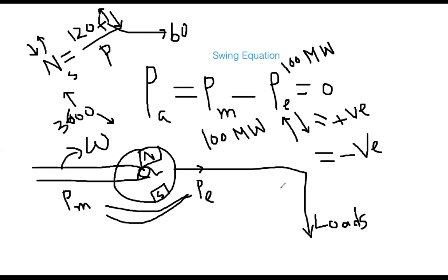So that was my question: do you think the frequency is always 60 Hertz? The answer is no. There is no short circuit, no open circuit, nothing happened. You are not noticing anything on the connected network. It looks like nothing happened. But still, if you see the frequency, it may not be exactly 60 Hertz, either a little bit higher or a little bit lower in real practice.